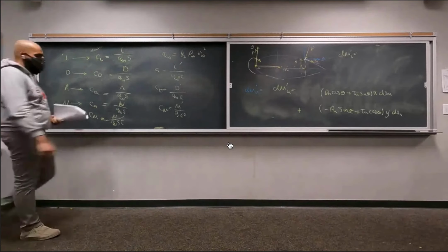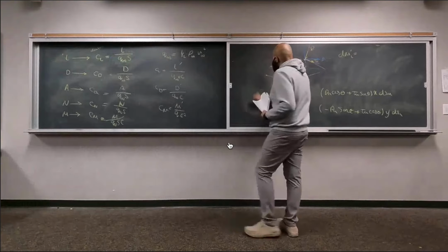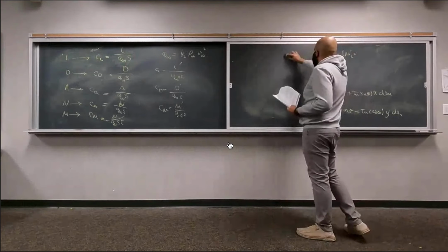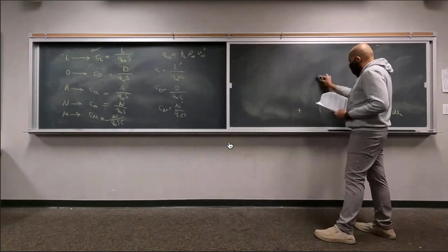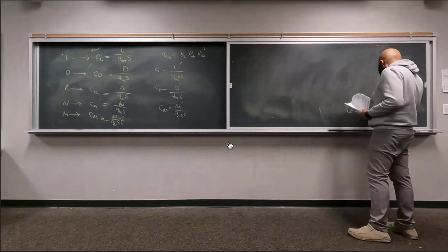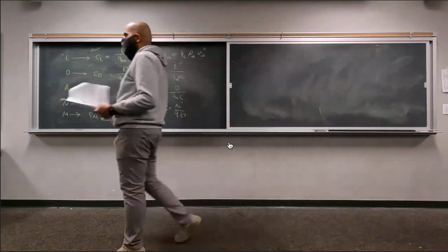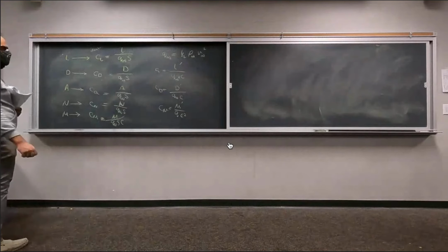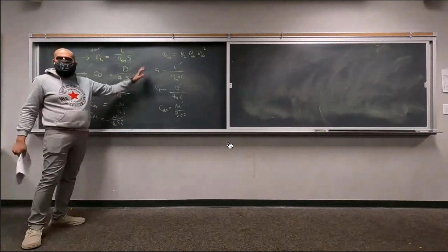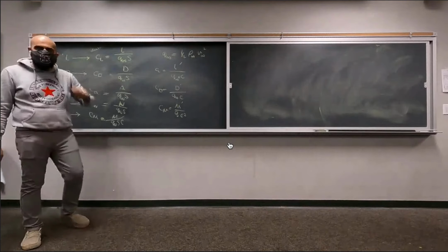Okay. So we have all of the equations that we need. We have the definitions of the force coefficients. We have the equation for moment per unit span. We have the equation for normal force, actual force. We have the relationship between lift and drag. So the next thing is essentially finding an equation for lift and drag coefficient as a function of pressure and shear.